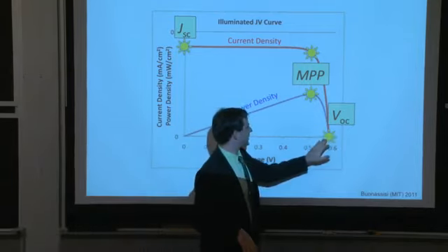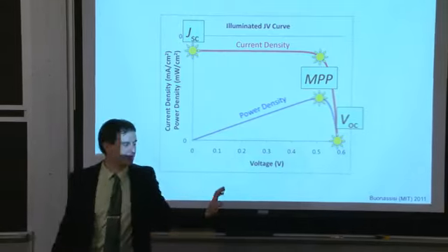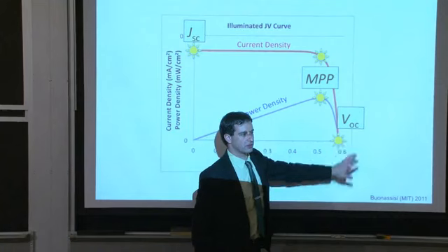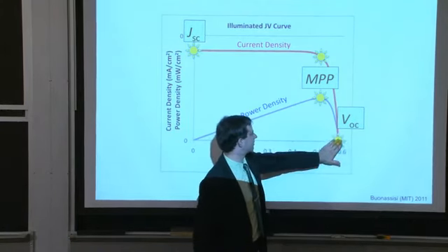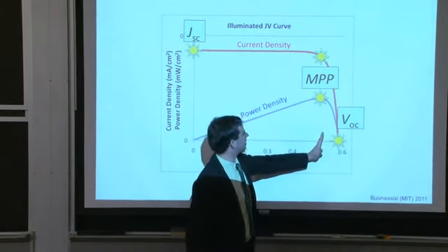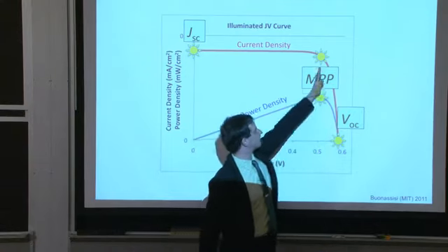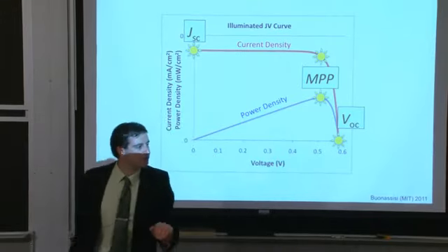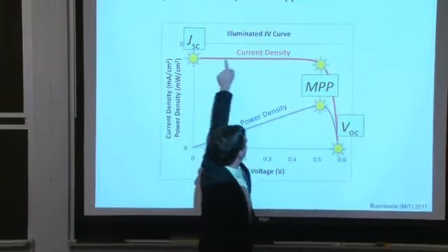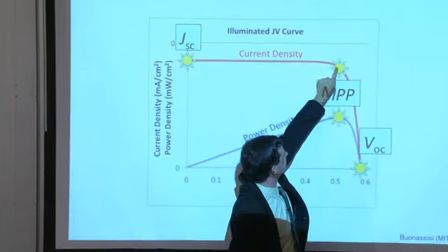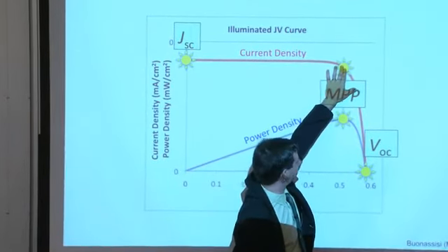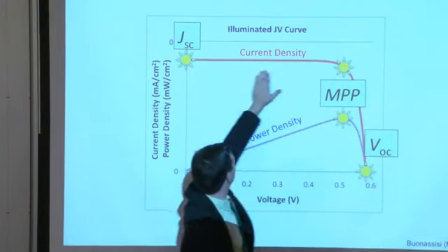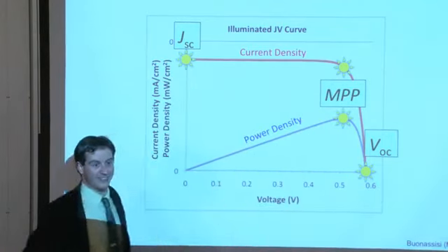And I can show you a very nice little paper that describes why that is. It essentially has to do in part with losses inside of the solar cell, thermodynamic limits of conversion inside of the solar cell device. Then what we've done is another additional discounting from the VOC to the maximum power point, which we've assumed is around 0.1, maybe 0.2 volts. Notice the shape of the IV curve right here. The maximum power point is interesting because the voltage at the maximum power point is almost the VOC in a good device. And the current at the maximum power point is almost JSC, but not quite.